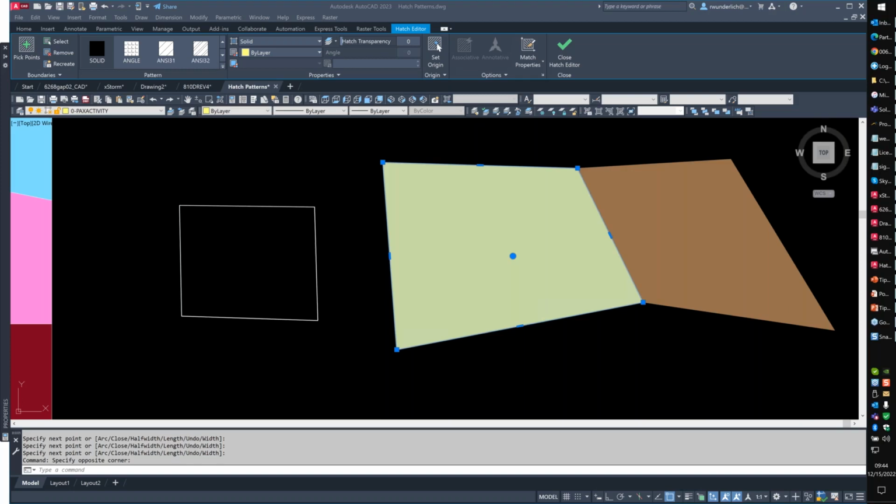-purge when you circle back. I type in -purge reg apps, then what? We use Carlson. When you do reg apps, it's going to ask you to select them to purge. Just hit enter, because there should be an asterisk within the brackets. It's going to then ask you, do you want to confirm each one? I usually say no. All right. And that should be fine, Devin.